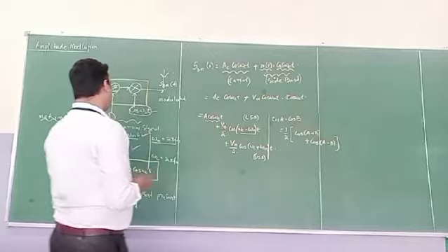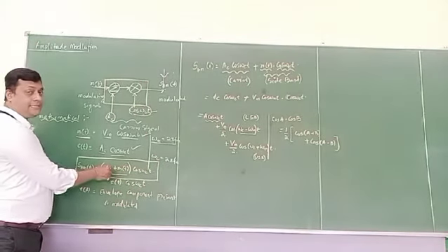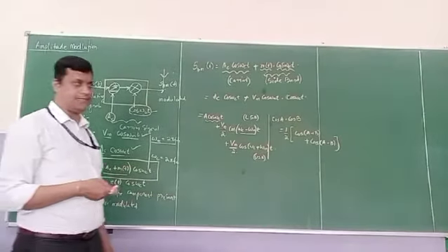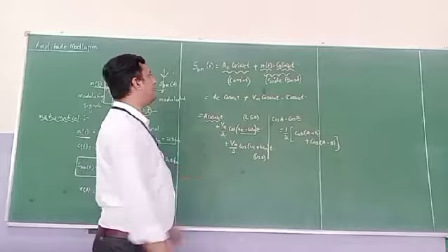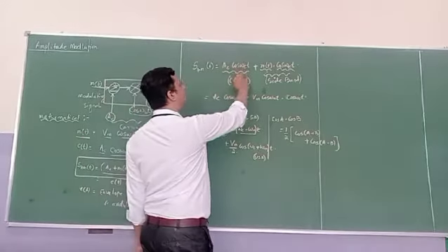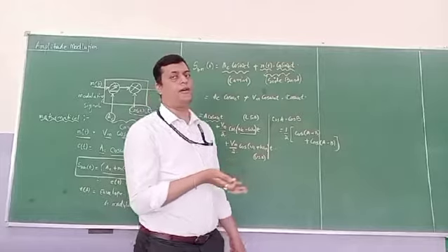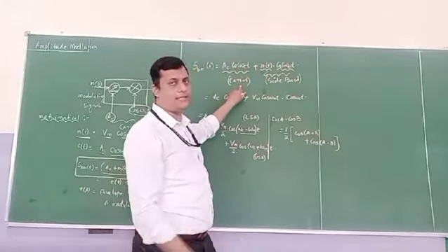Okay. Now one more important thing, if you take this A_c outside, that indicates our modulation index. For the time being, I have not discussed the modulation index. I have just expanded the carrier component with our modulating signal imposed on a carrier component. This is called our sideband. This is called our carrier.